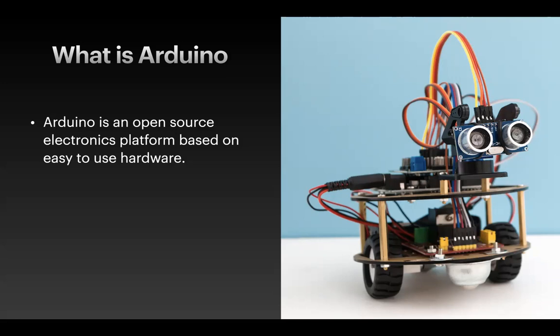And then of course, it's more like a hack. You can connect your usual computer cable and connect that cable to a power bank, right? So that is also another way of powering up an Arduino without using the computer. So you connect it to the normal USB port of the Arduino, and then the other end you connect it to a power bank, right? So I think you got an answer for your question.